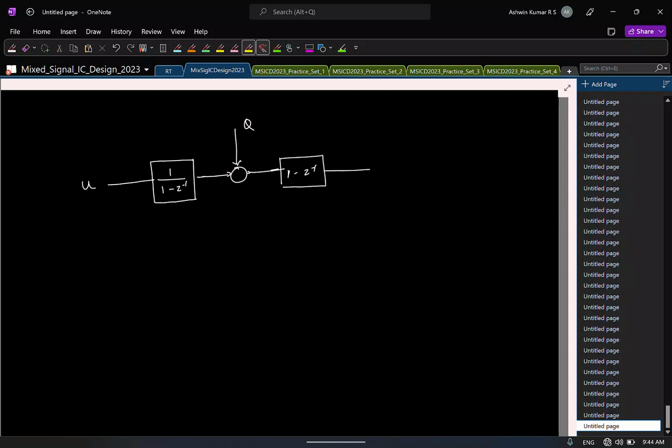But I am using an integrator in open loop. Do you foresee any issues because of that? It will not make DC equal to 0. Okay, that is fine. But let us say the input has a DC, what do you think will happen? It cannot be infinite. This will go to infinite, right? If the input is DC, the output will ramp up, and finally it will saturate your supply voltages. That's why in practice you never see integrators used in open loop.